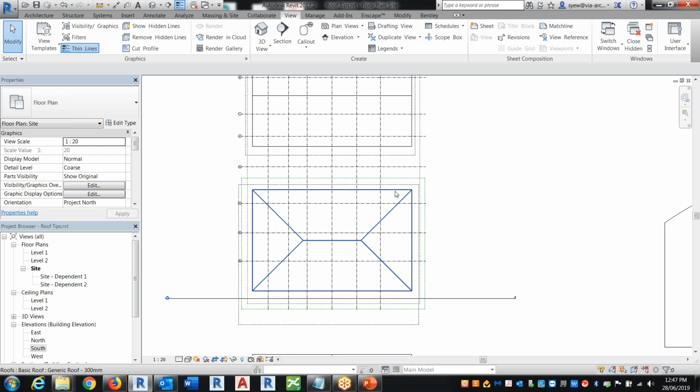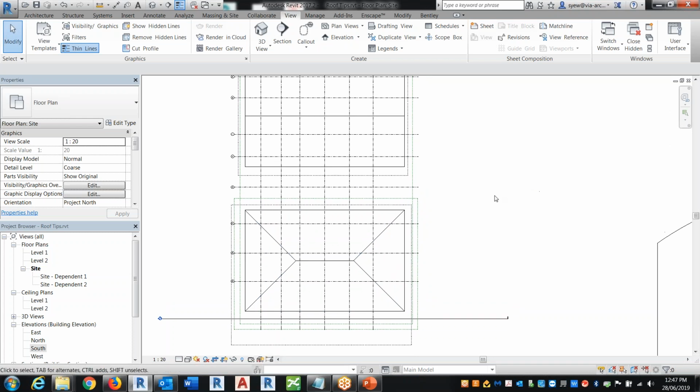I would just say if you want, just do multiple scope boxes, right? To control grids for, let's say, a core grid that you want to go from the ground level up to the roof. That would be one grid system. The other one would be parkade grids for the parkade, and then the other one would be just the typical tower grids. So you have almost like 3 sets of scope boxes just to get one or the other.